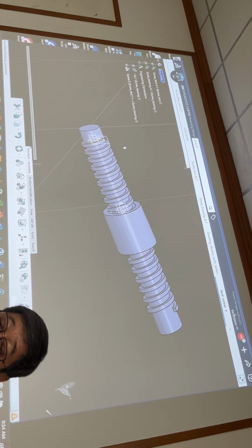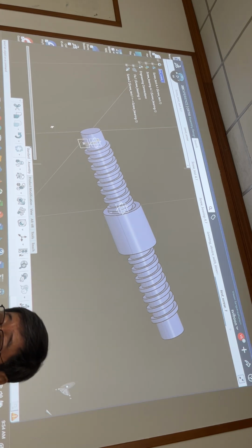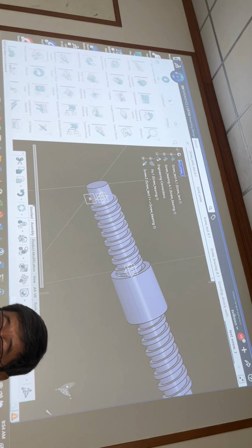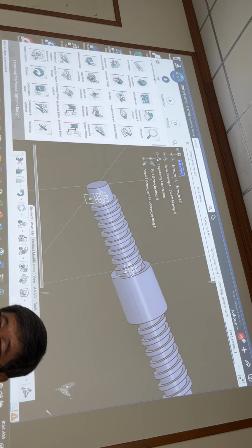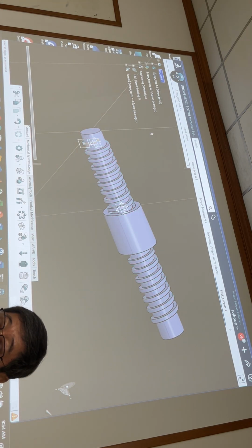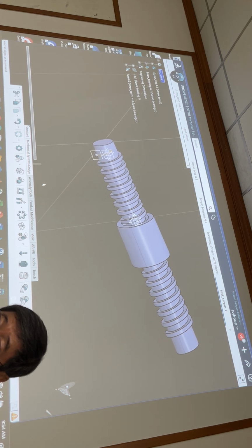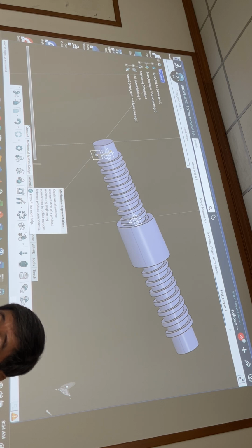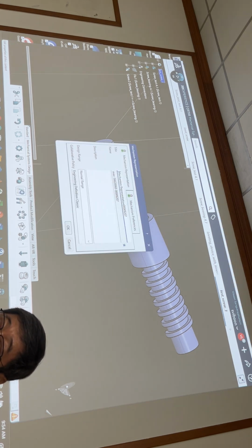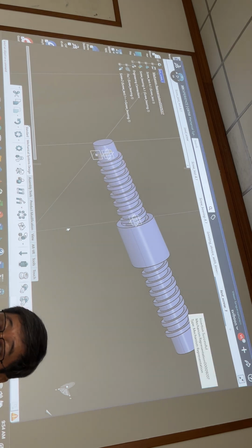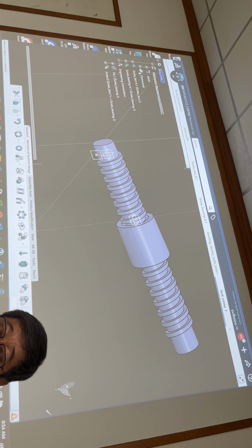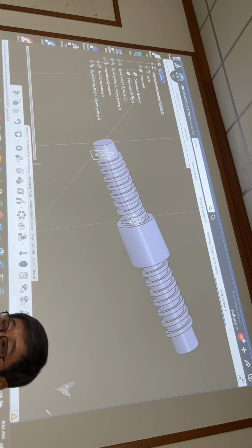Mechanism, right? If you just want to do the assembly, then just do assembly. If you want to do animation or simulation, you have to go to Mechanical System Design. You need three commands to follow. First of all, set the mechanism name. Let me use the default. That's okay. Inside this one, you already have commands there. You see, two commands.